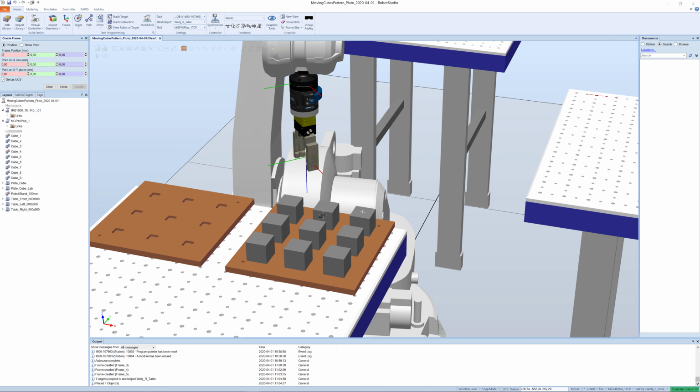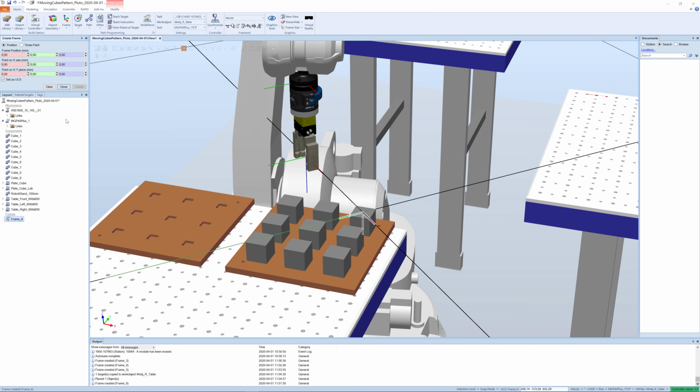Start over again there, and then click on the mid, that is the position, and then it automatically goes to the next one, which is x-axis, which is that direction, which is the same as this direction here on the frame, on the teach target before, and the xy plane is anyway here, but essentially this one here, which is the y-axis in this case, and great.